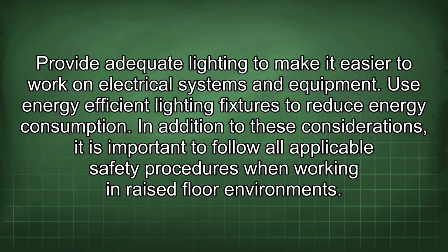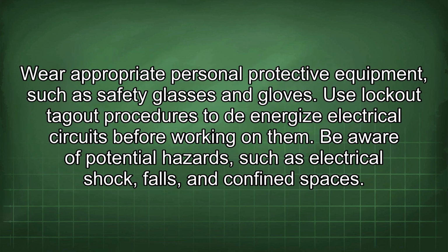In addition to these considerations, it is important to follow all applicable safety procedures when working in raised floor environments. Wear appropriate personal protective equipment, such as safety glasses and gloves. Use lockout-tagout procedures to de-energize electrical circuits before working on them. Be aware of potential hazards, such as electrical shock, falls, and confined spaces.